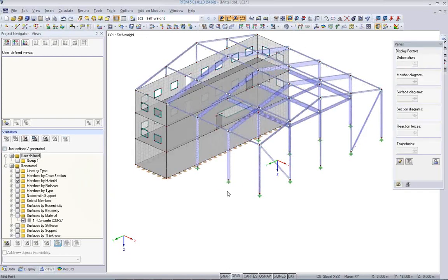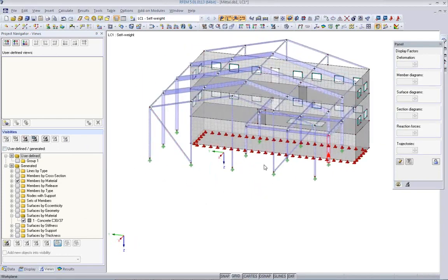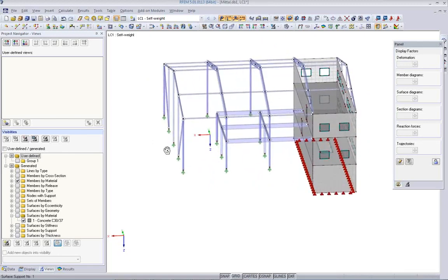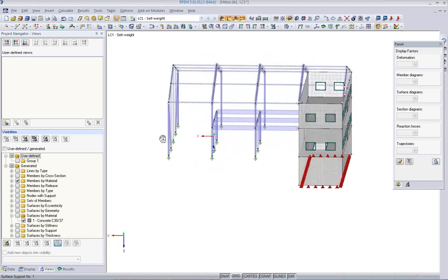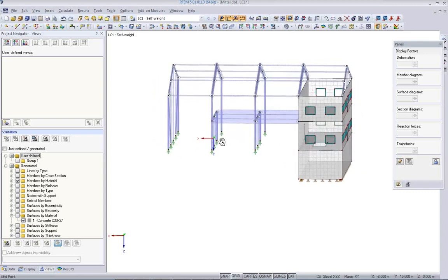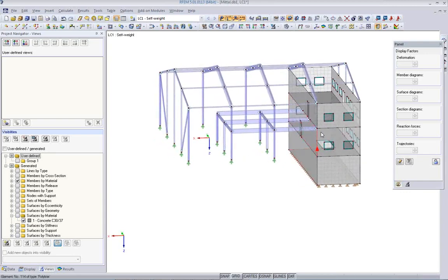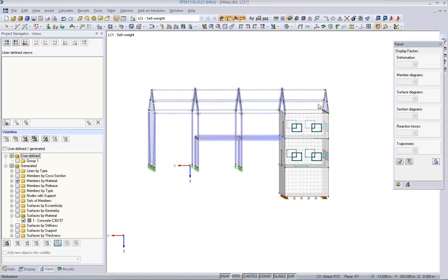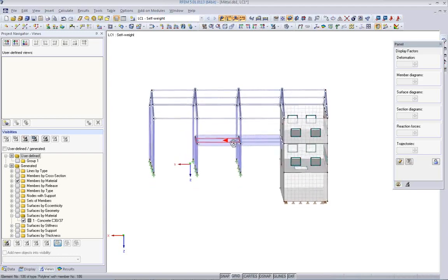First of all, maybe I've checked another thing from the structural point of view. I need some bracings here in the roof. Typically we have some bracings here. The first level here of the grid is supported horizontally by the concrete part here, but the roof structure maybe is a little bit unstable, and I would like to have a bracing here.